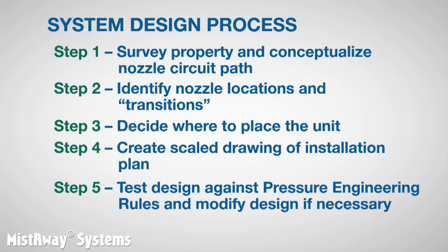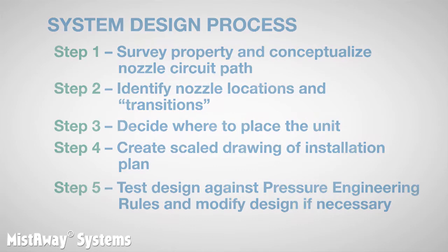Step 3, decide where to place the misting control unit. Step 4, make a scaled drawing of the installation plan. And finally, Step 5, use the pressure engineering rules developed in the fundamentals videos to anticipate pressure issues in your design and engineer around them.